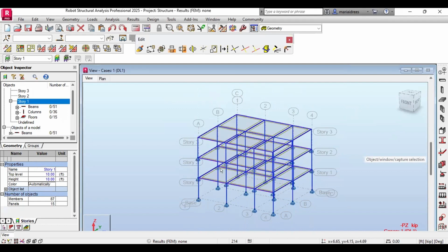The two stories have been added without doing any work, with just a click. Now I have also applied all the forces from all the loads from story 1 to story 2 and story 3. So the work has been simplified, but here I can change the loads in story 3, and I can use roof load instead of live load in story 3 if there is no one there.